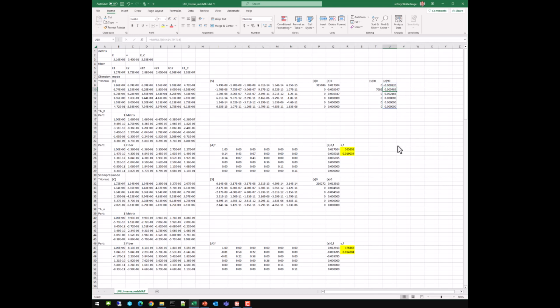But that isn't what I want homogenized. I actually want the strains of the matrix phase. So I need to calculate the amplification matrix of the matrix. So we'll just transpose our stored matrix here. Okay. And this will allow us to calculate the strains of the 90 degree of the matrix phase.